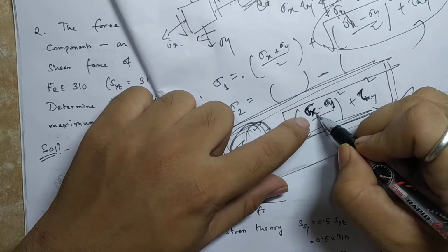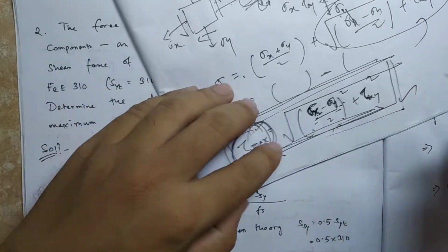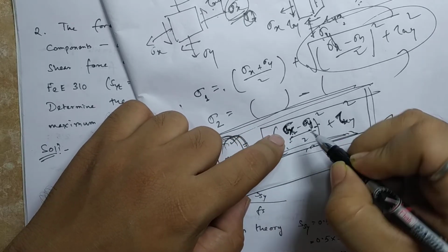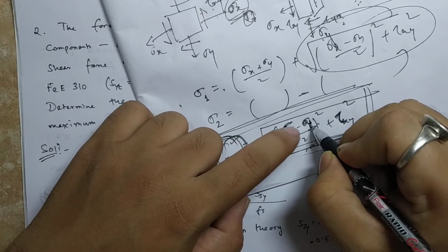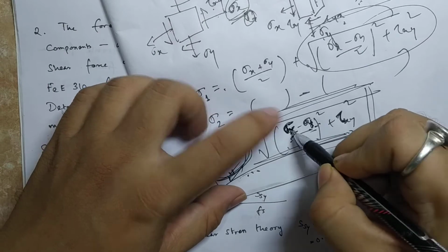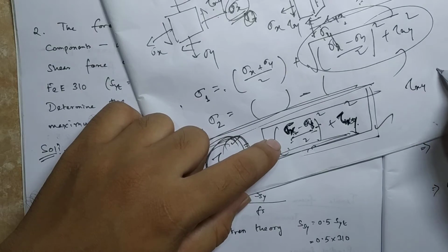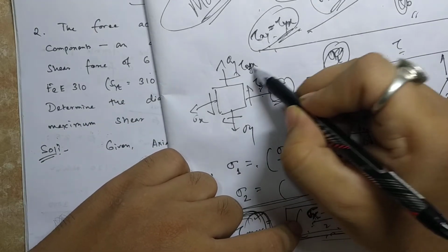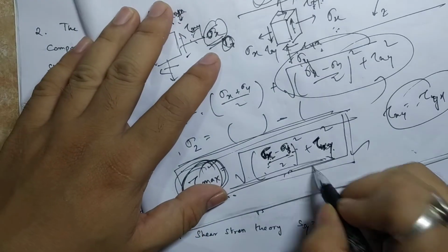Now this is for biaxial stress, x and y axes. We apply one tensile stress in the x direction, and in the y direction also we apply some tensile stress. Tensile or compressive, it's up to you, but it is normal to the area, and one shear stress is present. Since tau xy and tau yx are both equal, you can just take any one of them. So this is the complete state of stress, and this is how we combine them.